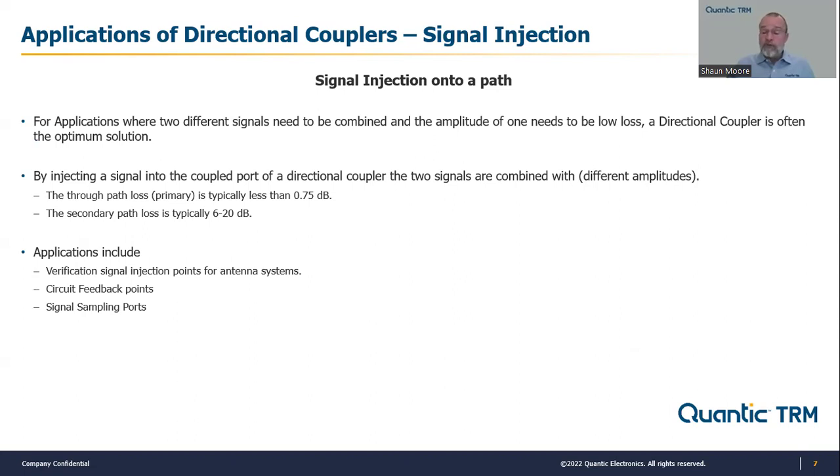You can put these multiple devices on multiple lines and start doing some software corrections for amplitude and phase errors that can happen going over long transmission lines from apertures and from antennas going back down towards the avionics.